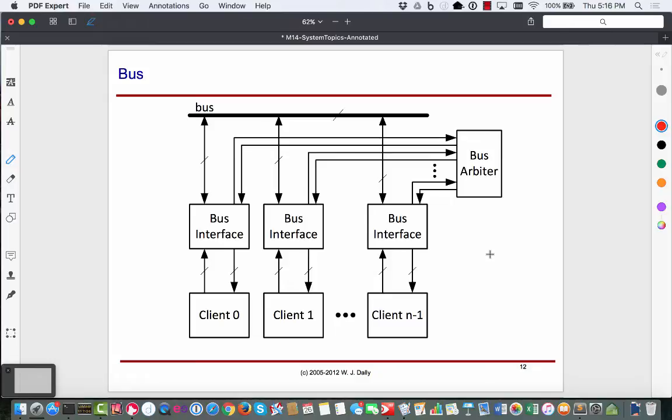So what would happen in a system like this is, there is this guy called the bus arbiter. We saw an arbiter. What does an arbiter do? Depending on if it's fair or not, it'll basically just pick the first bid. At a higher level, what function is the arbiter providing? Basically, it just picks one of n requesters. It is guarding a resource. There are many entities competing for it. It picks a winner.